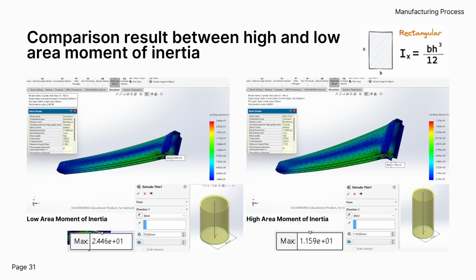Imagine brittle and flexibility. You want flexibility rather than brittle, and that's why for material, we choose PP copolymer. If you remember from previously, PP copolymer is also more flexible, so this is what you want. You will have displacement, so do not worry, but it's not really a concern for this tutorial at least.